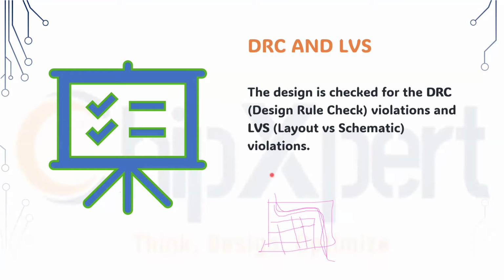The technology will give the guidelines for each of the nets and wires. If there are any shorts or wire-to-wire connections, all this will be checked. You are good if there are zero violations, zero routing issues or wiring connection issues. Then you check for layout versus schematic issues.